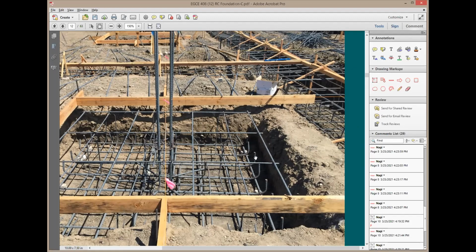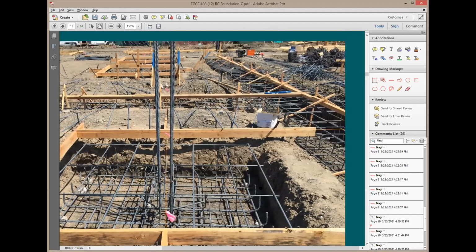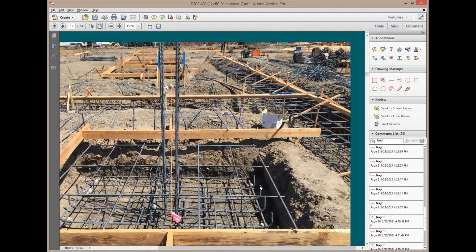Yeah. And if you have a problem with water seepage, if this can be an issue on a site, you don't really just do this. Once you come here to the bottom of the hole, you need to put moisture proofing, right? You need to isolate the concrete footing from any moisture. So what you can do, you can put the lining right here below the concrete footing and then build on top of it if this is going to be truly an issue. Got it. Like that geotechnical fabric and stuff. It's going to be like visqueen, like plastic. The fabric that you're talking about here is not mainly for moisture proofing, it is for different reasons. All right.